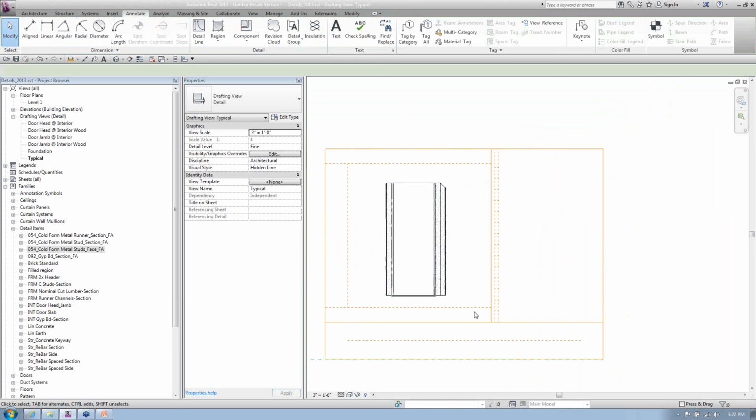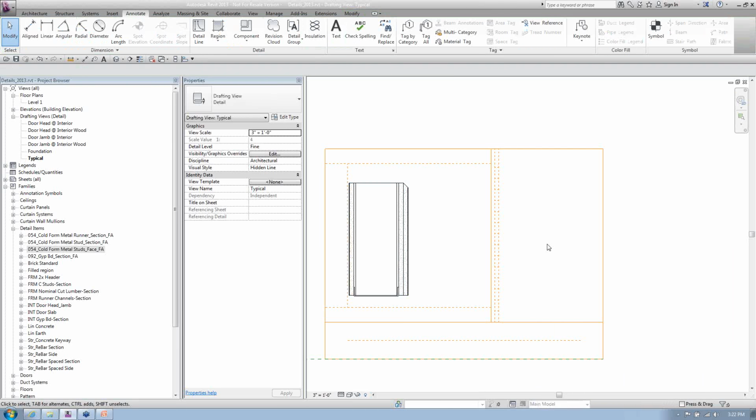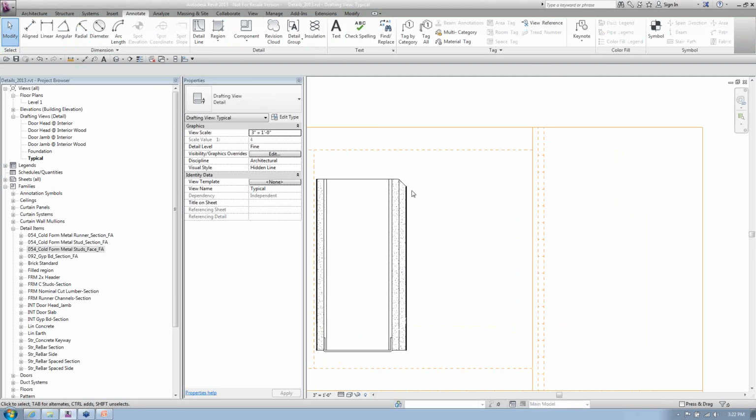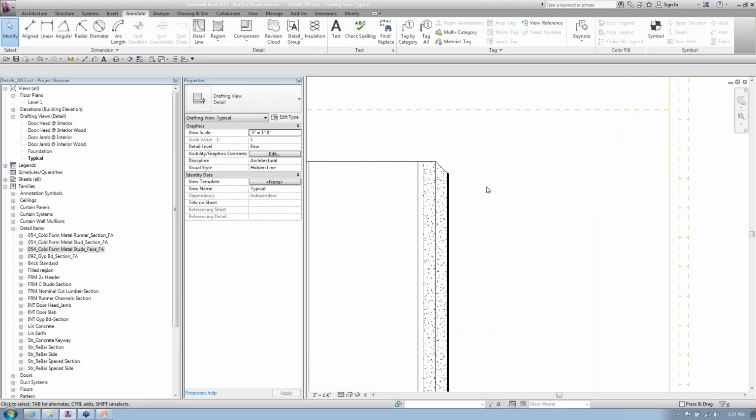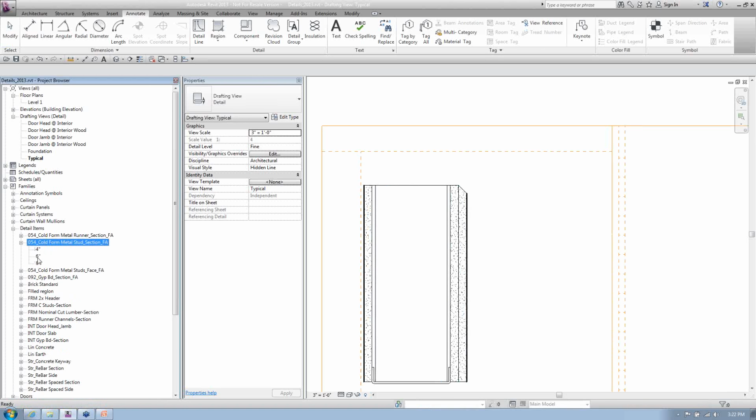Since I decided we're doing an inside corner, of course now I did a hat channel, whatever, we'll start going through and doing some more detail components. So as we go through, do these detail components, it's a whole lot of grabbing this component, grabbing that component, doing it again. Maybe I wanted to come in here and throw a C-stud on the side. So same type scenario, we'll grab a stud section. I'll grab a 6-inch section stud.